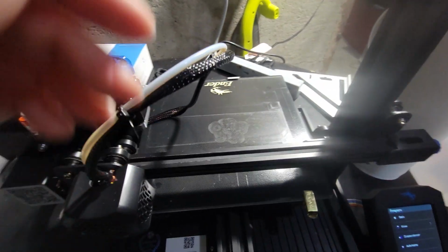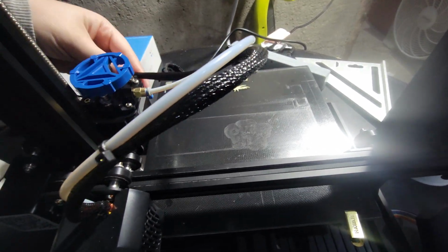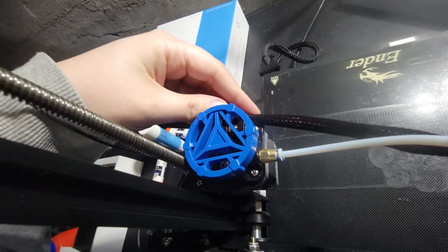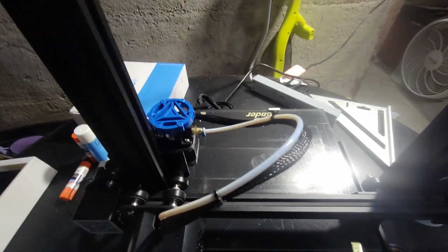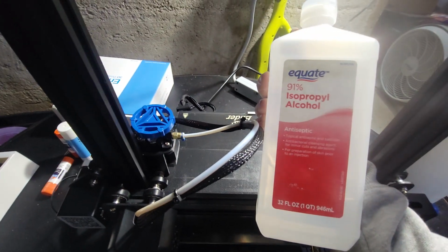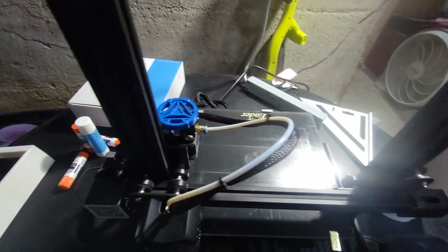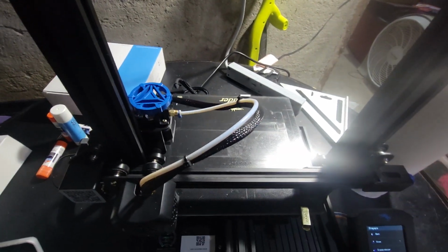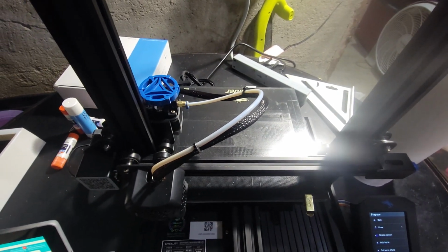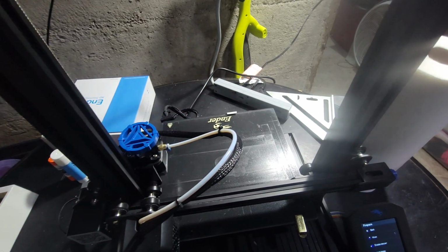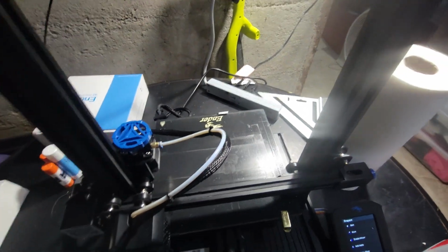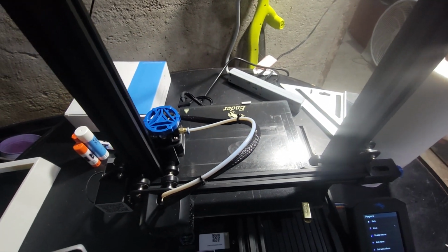Next, I will want to clean off my build plate and move this back to its housing, which is against the clip. So, to clean your printer, you will use isopropyl alcohol to make sure it is clean so your print will stick. If it does not stick, use glue or hairspray. I don't have that issue, so I will not be needing that.